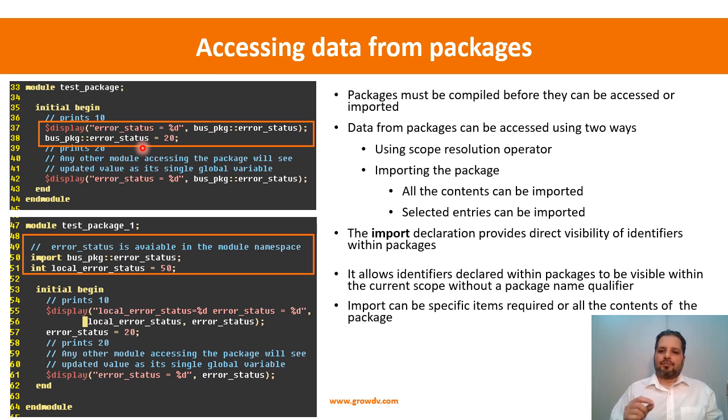So in a way you can think that the packages are never instanced. It's just one copy of whatever you have declared within the packages. Especially I'm talking about the variables. The other things are okay, tasks and functions are fine, but variables are just one copy. So if you change it at one place, it reflects at the other place as well.